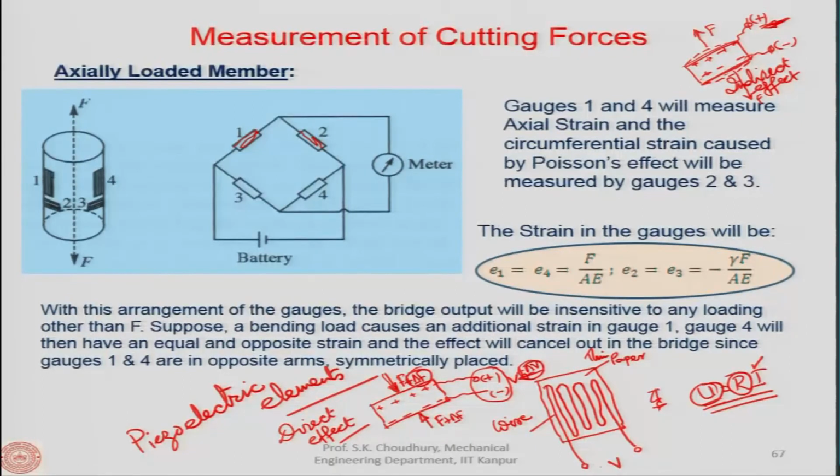So, this high frequency vibration can be created by using this indirect effect of the piezo elements, when the current is passed and the whole thing is expanding. Now, if you are changing the frequency of the current, then at that frequency it will be expanded and come back. So, that itself will be the vibration.